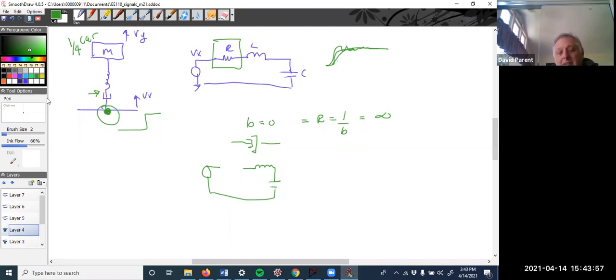So that's if it fails in a way that it doesn't pass. But what if it fails, right? That it doesn't slow it down at all. It passes everything, right? If it's passing everything, well, there might as well be no damper there at all. It's as if it were connected by a steel rod. Well, then that means resistance is 0, right? And we have this, and we have our out of control system. Okay.